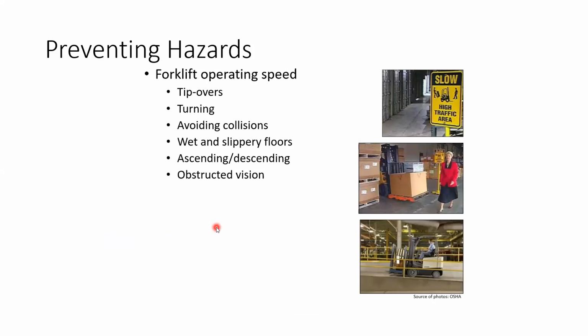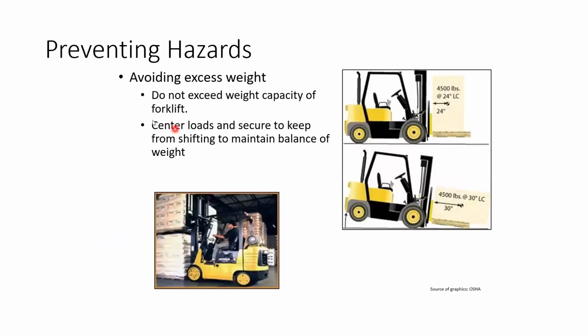Forklift operating speed, tip over, turning, avoiding collisions, wet and slippery floors. You should take care, as all of this is hazards. Ascending or descending, all of this is hazard, if you ascend or descend with the forklift. Obstructed vision is also a hazard.